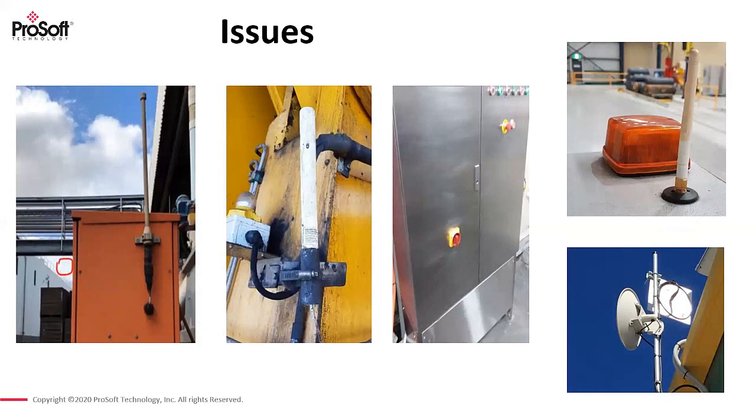Also, it's going to be a weak signal because that signal, both of them, are spread in all directions and it's picking up interference. So if I had to do this radio link, I would want to use MIMO here because of the metal and try and bounce it off the buildings. Try and get a clearer line of sight and use a directional one like a panel antenna. Get a much stronger signal and less interference.